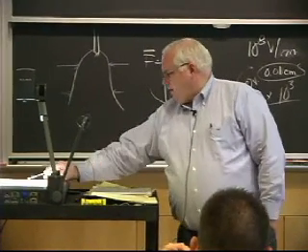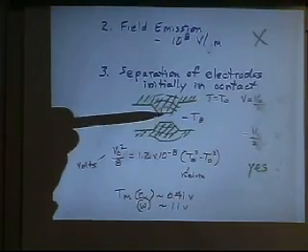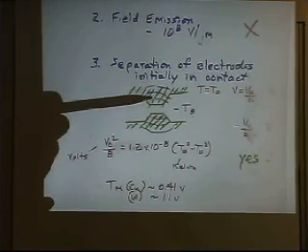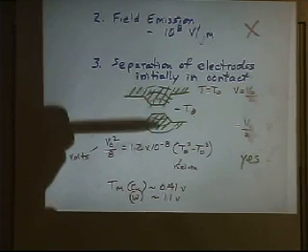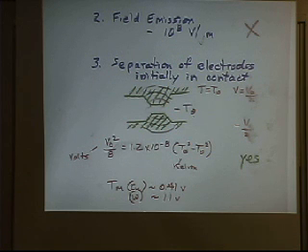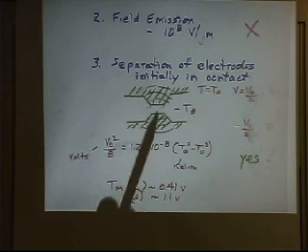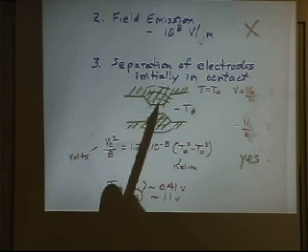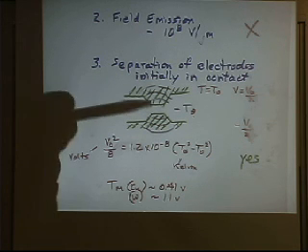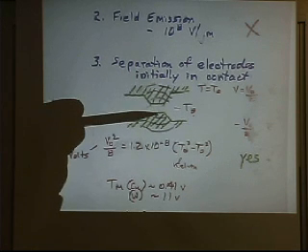And the way that works is if I have two asperities and they come into contact and then I pull them apart, as I separate them, the resistance goes from a low resistance to a very high resistance. There will be some current as I first touch, even though I only have about 2 or 3 volts, or actually I have about 60 volts, but even with only 2 or 3 volts, there's enough current going through here. As the resistance goes from the low value to the high value, you get to some optimum resistance in between where there's enough power to essentially vaporize these surfaces.